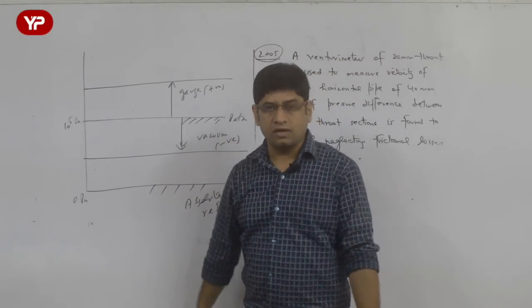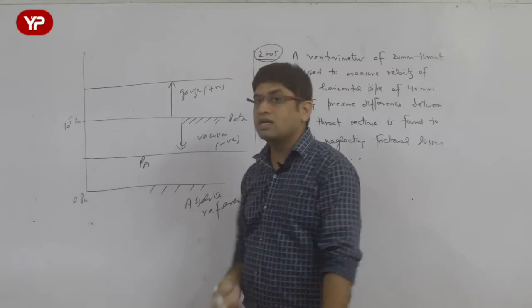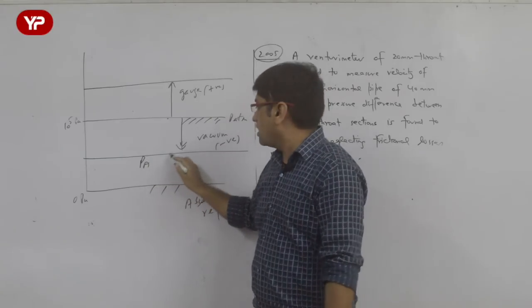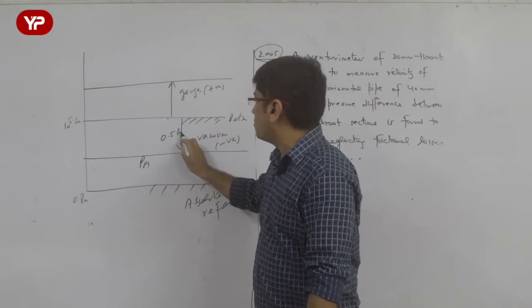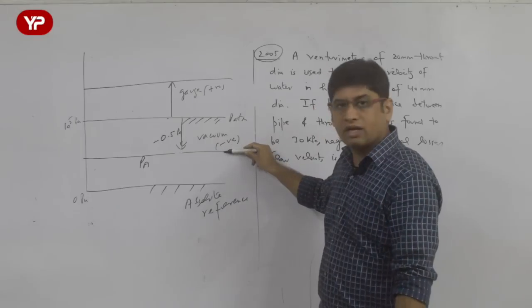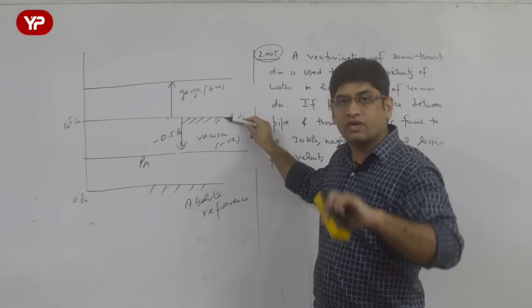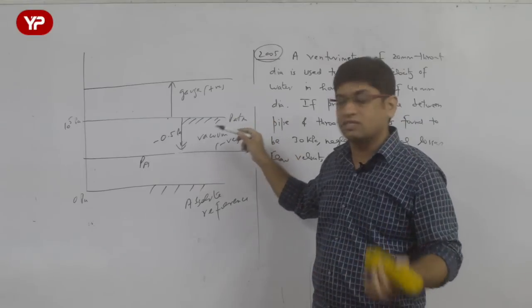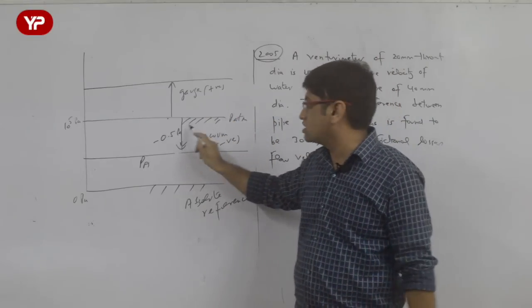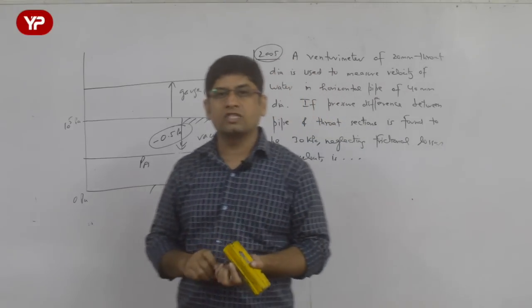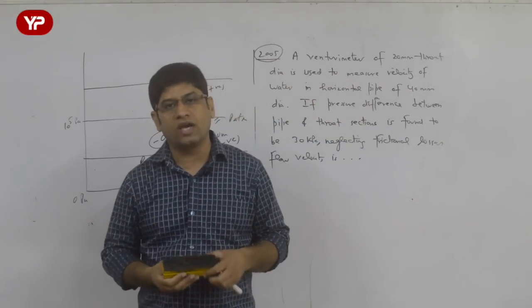Now in this situation, the pressure at A was negative pressure. Atmospheric pressure is this and this is the negative pressure, and hence I am getting 0.5 Pascal, which is negative. That means I am seeing it with respect to atmospheric reference. If you select atmospheric pressure as 0 reference, you get the negative pressure. So in this case, I am getting suction pressure, which is the negative gauge pressure or the vacuum pressure, 0.5 Pascal.